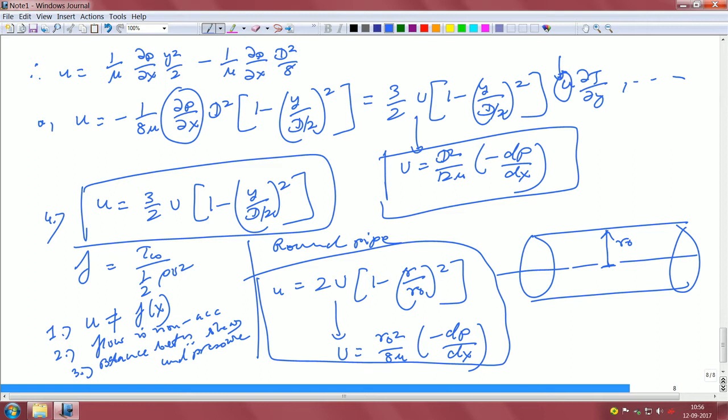This u can now be taken and easily applied over there, right. You can solve it a priori, and you can take that solution and apply it in the energy equation, provided that you are operating in the fully developed regime of both the cases. That means you are in the hydrodynamically fully developed regime, and of course the energy equation is also in the thermally fully developed regime. Okay. Or it can be the situation, at least the flow has to be hydrodynamically fully developed in order to apply that u and directly place it over here. Okay. So, that is what we have done, and for the round pipe we have given an expression as well.